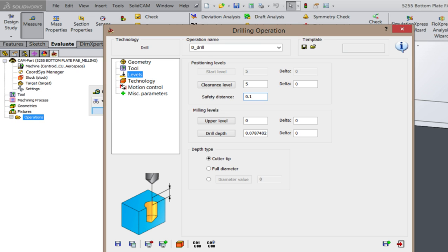It's going to start going 0.1 inches above the part. Now, that's not very far. 0.1 inches is this far, 2.5 millimeters. Okay, so if that's too scary for you, if it's going to move really fast and you don't think you can stop it before it's going to potentially hit the part, then you might want to increase the safety distance.